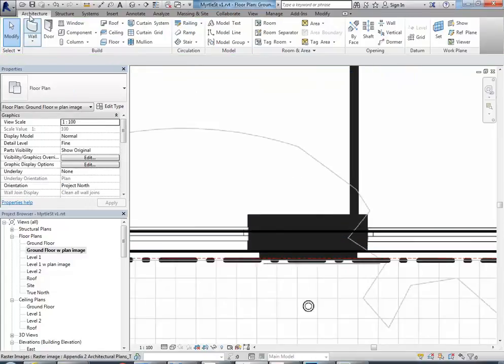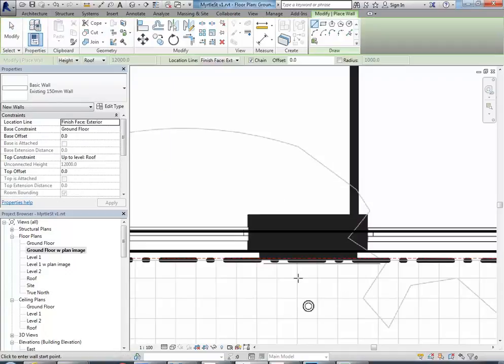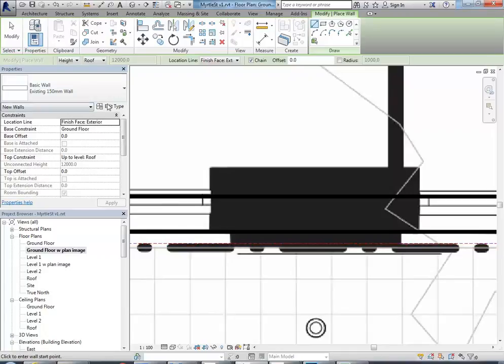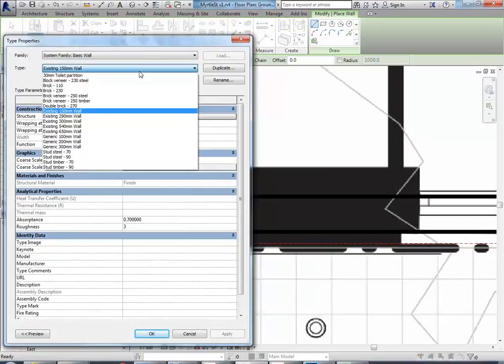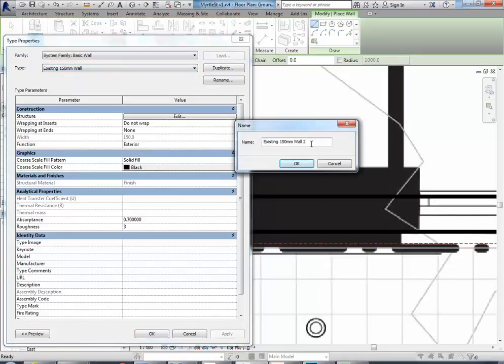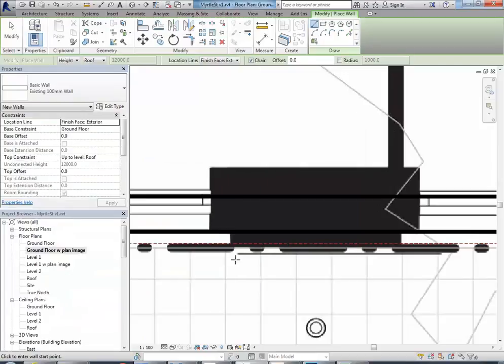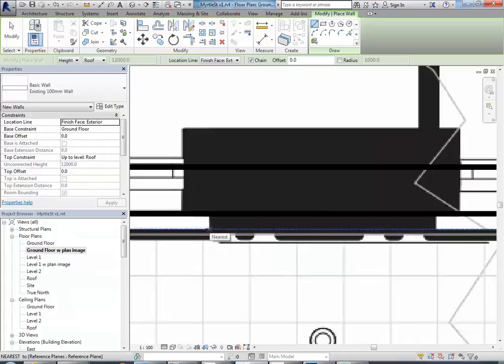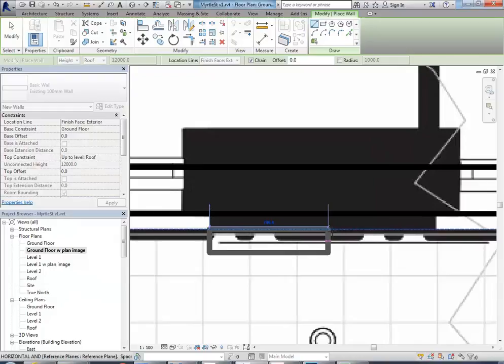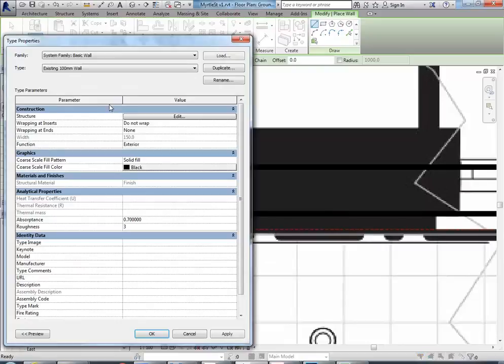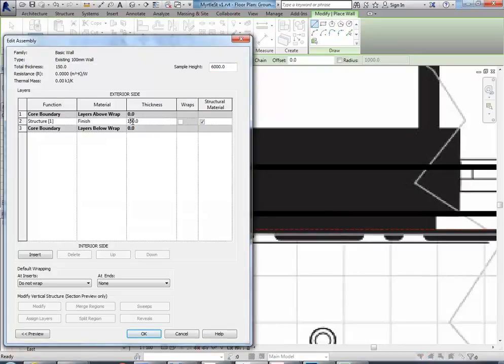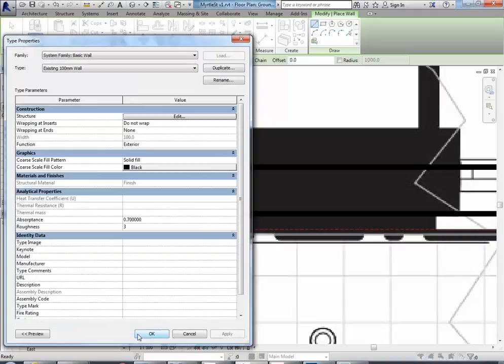And so again, just maybe to do the piers one more time, using the wall tool. Maybe I'll move this one 100, not 150, so I'm going to make yet another wall type. I don't think I have an existing 100. No, duplicate. So you might end up with quite a few wall types. And I'm going to draw from this corner here, going to the right. So do you think that's a problem? Well, there's a couple of problems. I didn't change the wall thickness for a start. I changed the name, but I didn't change the thickness in properties there, so that's obviously a problem.